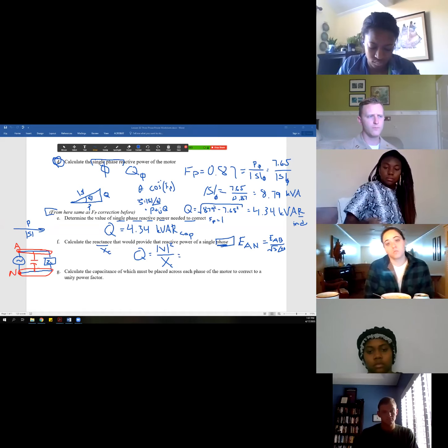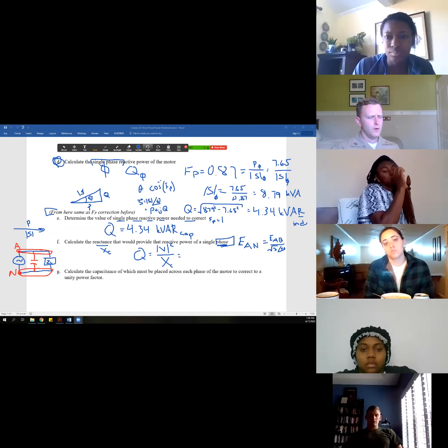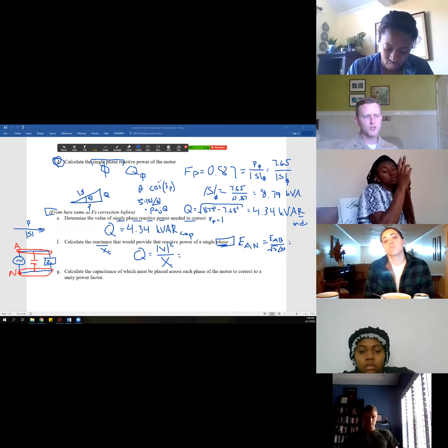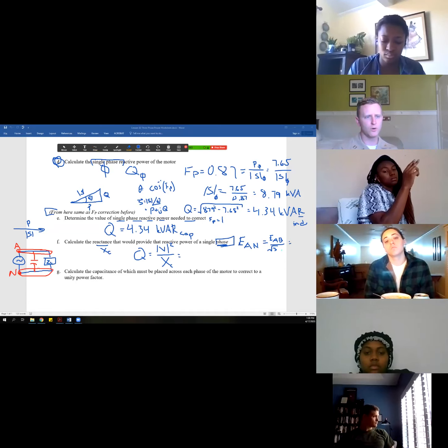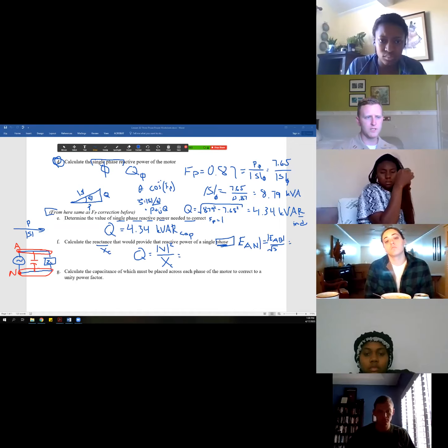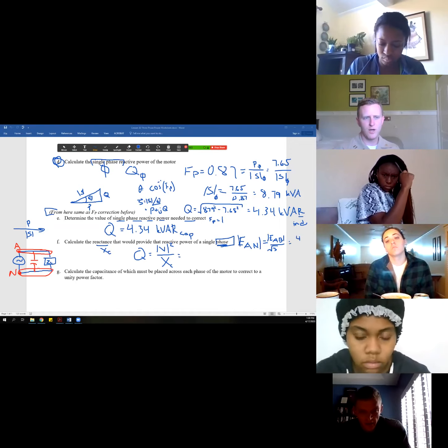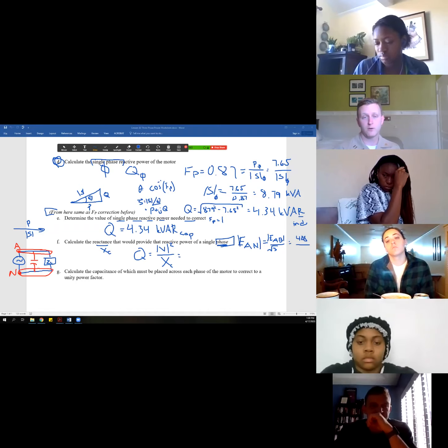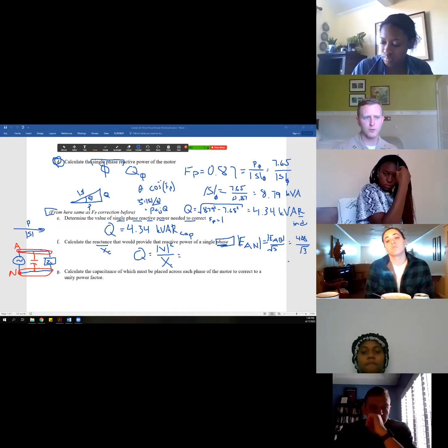So this EAN that we need was the EAB. And since it's just the magnitude, if I wanted, I could just ignore the angle 30 because I'm just looking for the magnitude of the voltage. You don't have to take that shortcut if you don't want. Do it with the angle, just make sure that when you solve it, you pull the magnitude out.